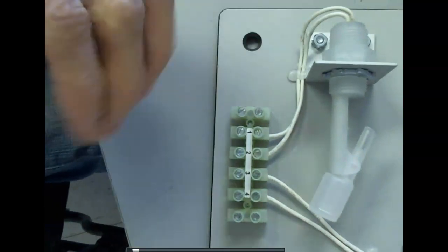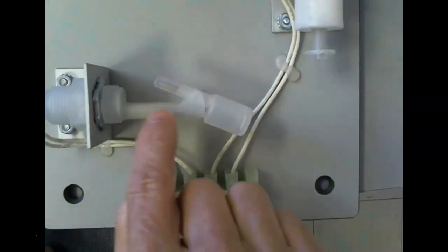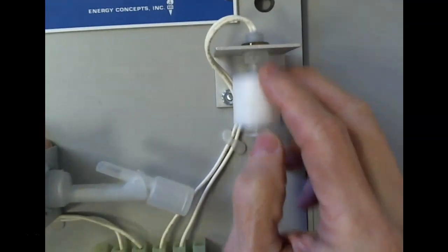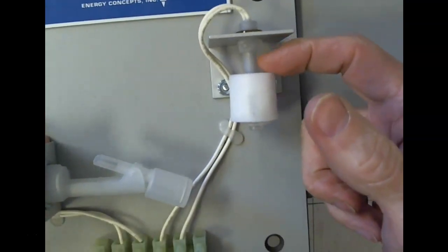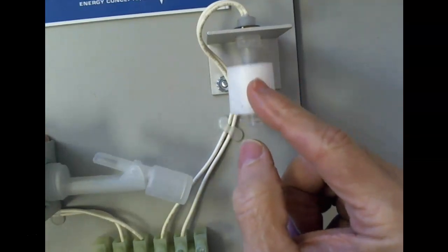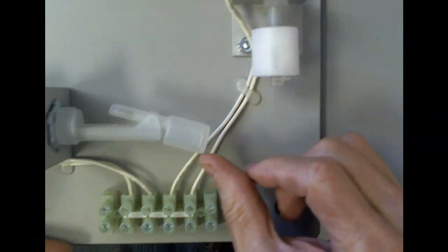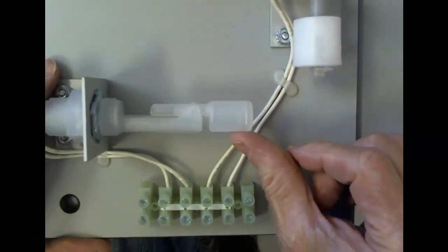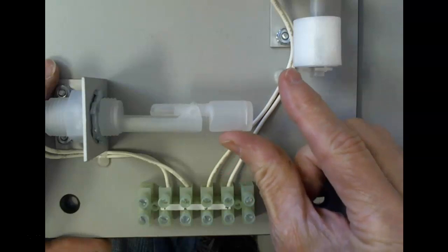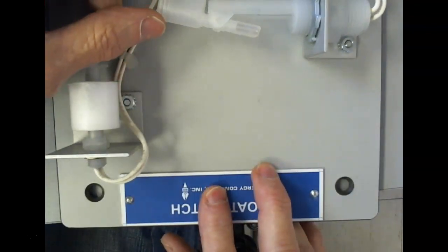So this is the one we have, and it's actually got two sensors on it, and it uses a magnetic reed switch. So these are actually magnets, and then the reed switch is here. On this one, the reed switch is inside the actual tube, and then the magnets are on this guy right here. Okay, and that's all it is to it. So this one, if we mount it like this, it's going to look for it to be at a certain height, right? But remember, on this one, we can also mount it what? So if we mount it like this, then it will look for it to drop below a certain height, right?